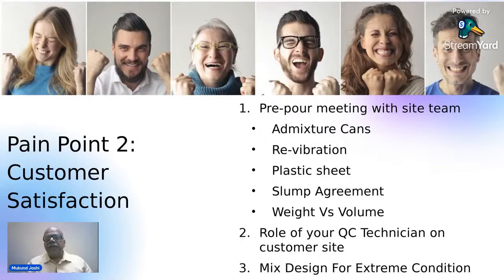This means within 1 hour, you will cover the concrete, and if there is some delay, you will sprinkle the water on top after the revibration is done and then cover it with plastic sheet. So we are protecting the concrete from these climatic conditions, which are not going to give problem to the client. Of course they will give problem to him if there are cracks and the water leakages happen.